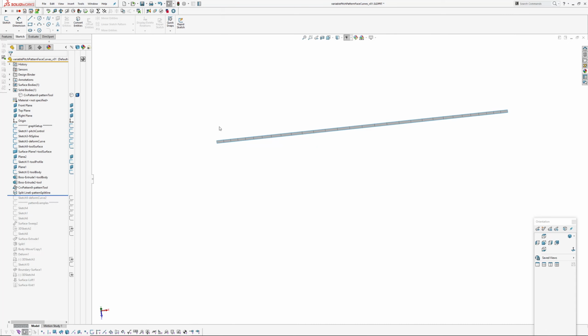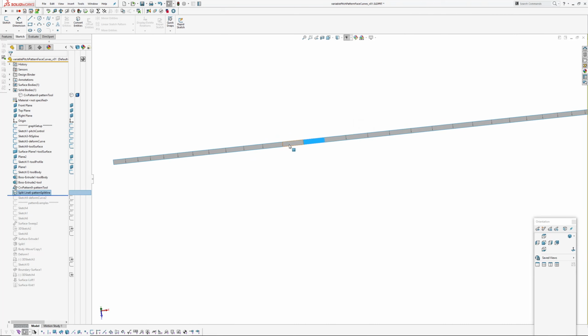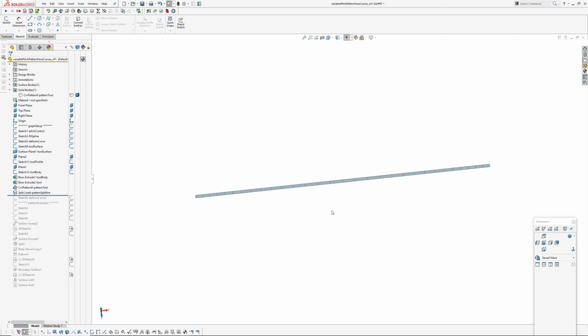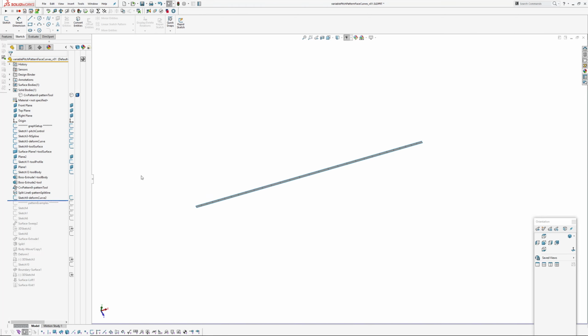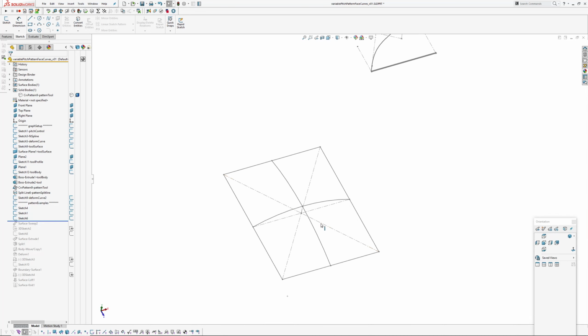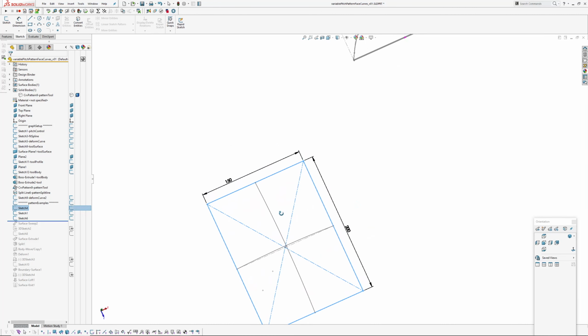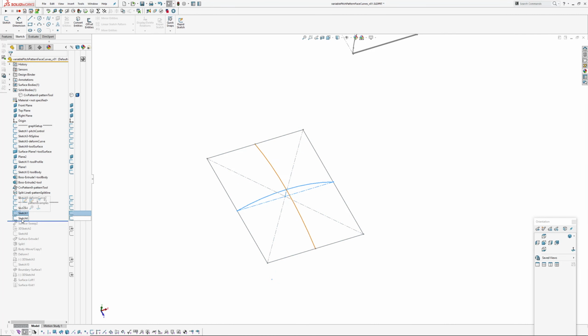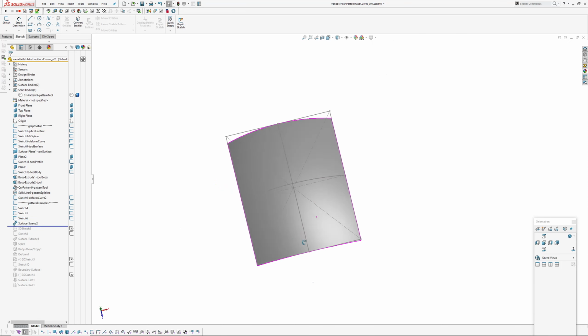The idea is I take this tool surface, which is split into variable length sections, and then that gets deformed onto the geometry where I'm actually going to create the ripples. The next thing I've done is, when you use the deform tool and use curve to curve, you need a base curve and a target curve. So this is my base curve, which is just along one edge of the tool there. It's just a line coincident to each end. And now I'm going to make a sweep. As you can see, I've got a boundary rectangle and then a sweep section and a sweep path, and I've just created a domed surface.